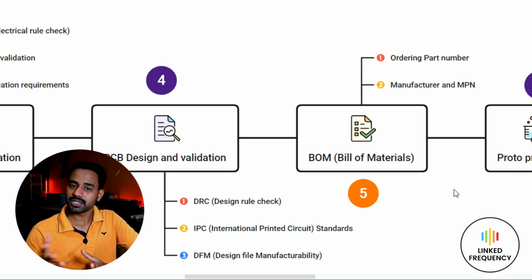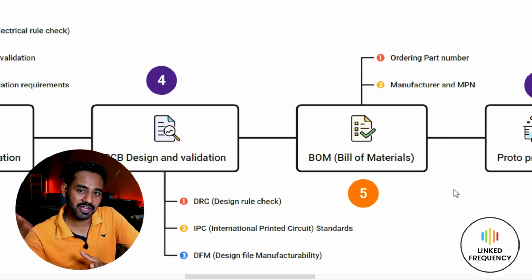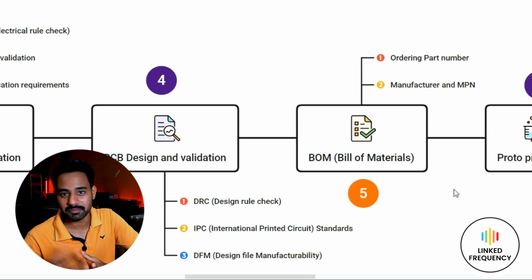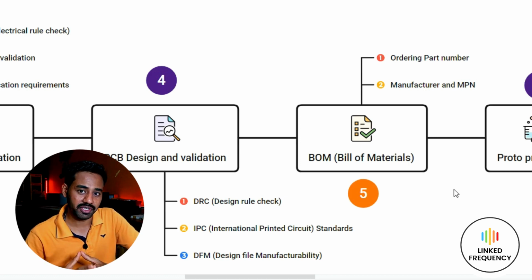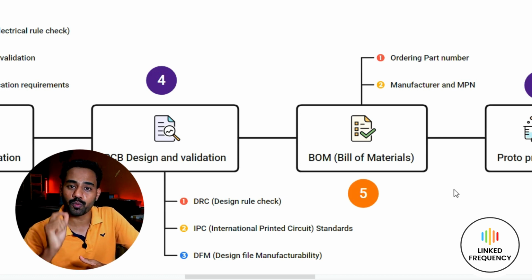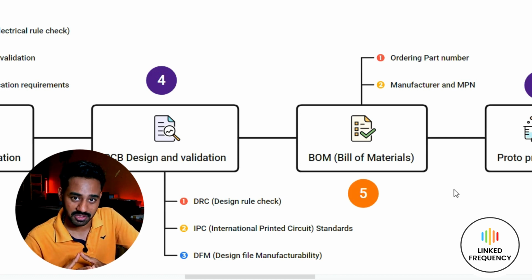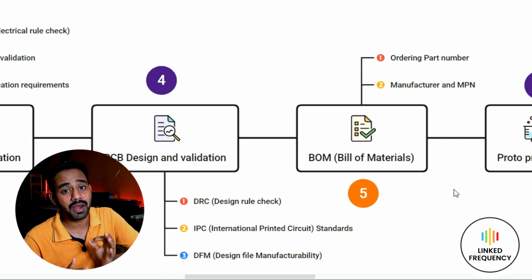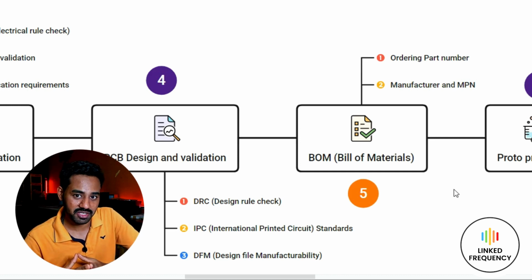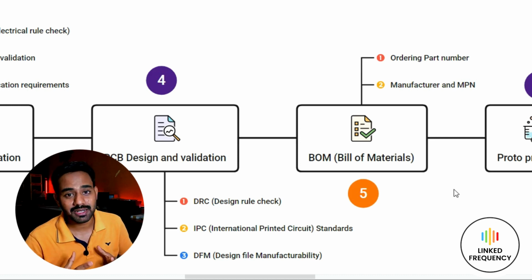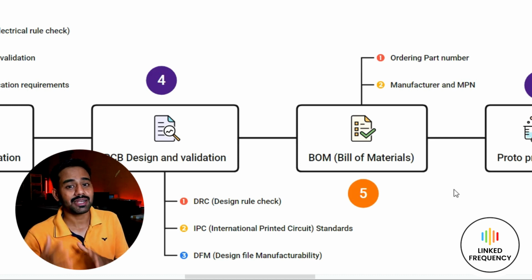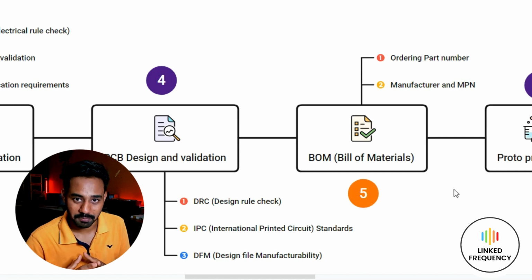Say for example, right now we are doing a prototype, so 7805 is quite easily available and we procure it, install it, and try our product. After that, if you are going for mass production, say 1000 units per month, at that time we need to know which manufacturer we need to select for this particular component and what the part number is for that particular manufacturer, because for the same component from a different manufacturer, the part number would change, and that kind of part number is called a manufacturing part number.